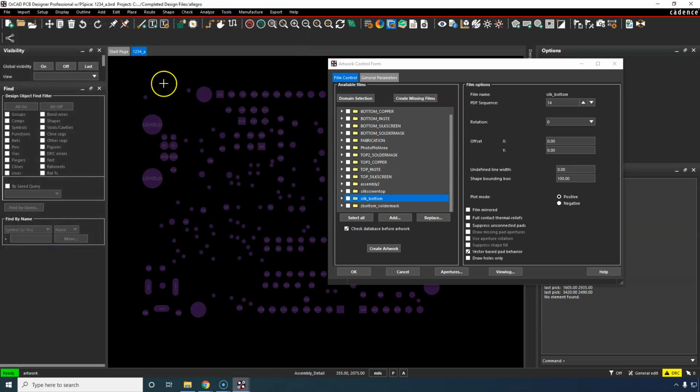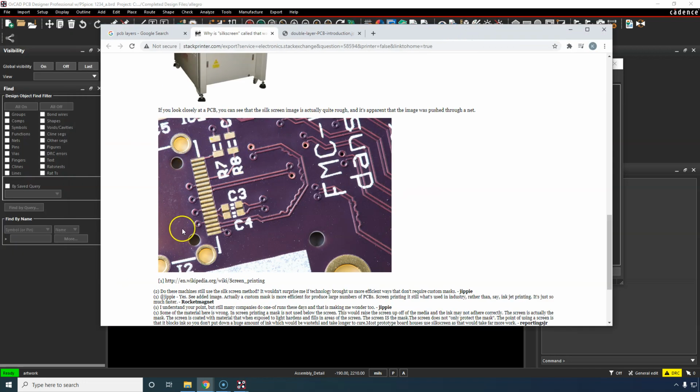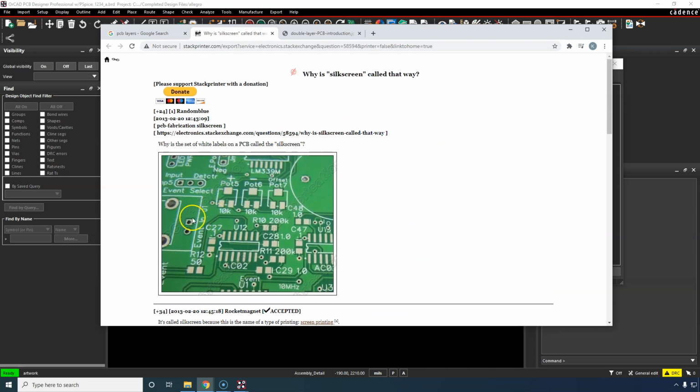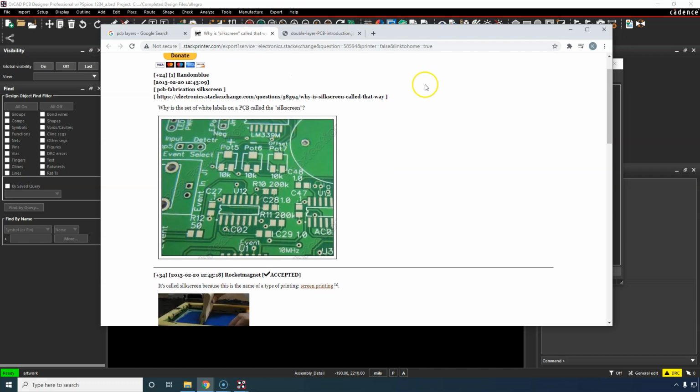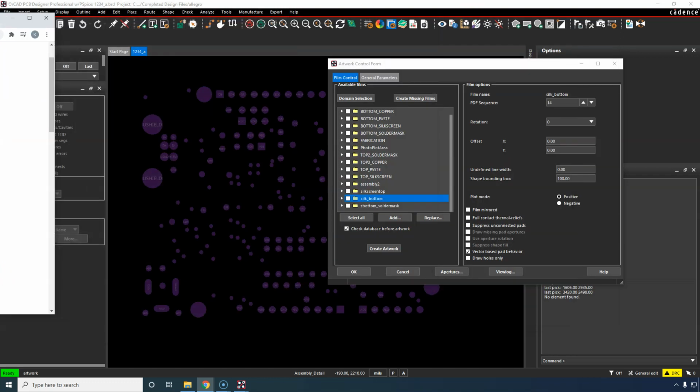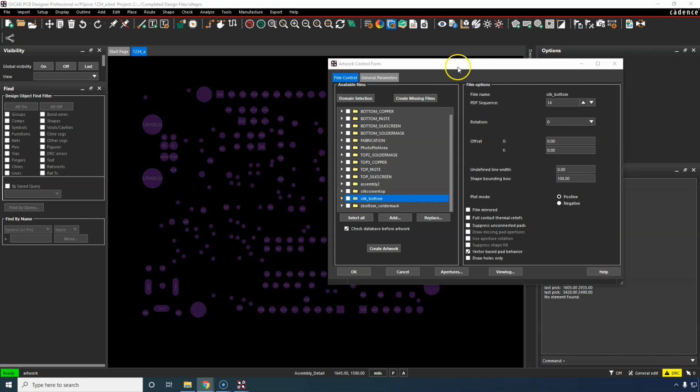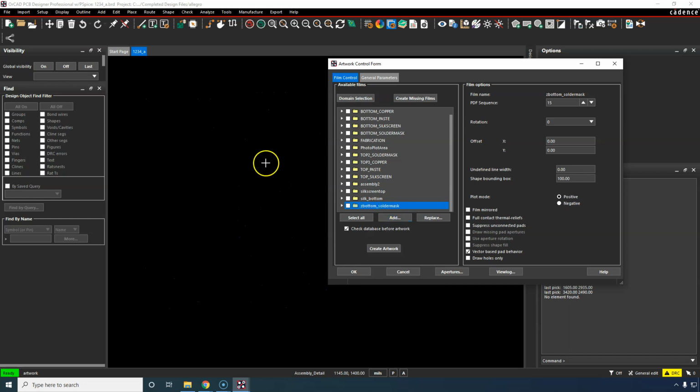Why is that? Because some devices for their package footprint will want big areas exposed, where they'll want the copper exposed. I don't have any examples here, but you know, those big MOSFET pads or something like that. They have gallium arsenide or silicon carbide MOSFETs with those big exposed pads. Yeah, something like that. Anyway, so there's that. What does the view look like? Display for artwork check. Nothing shows up because I have no parts that require opening large like that.